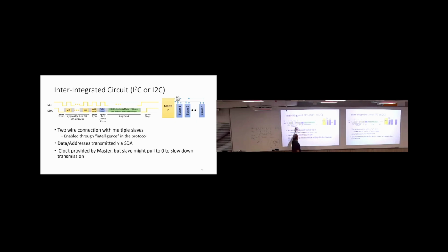So a lot of the things that are transmitted are overhead. So it's just slower because you need more clock cycles to transmit all this stuff before you can send the actual payload. So there is no clear answer which is better, it's really use case dependent. But most of the systems nowadays have some UART and some SPI implemented.